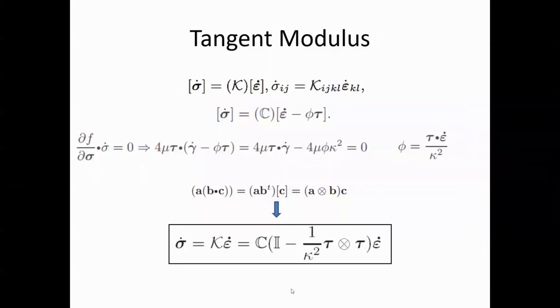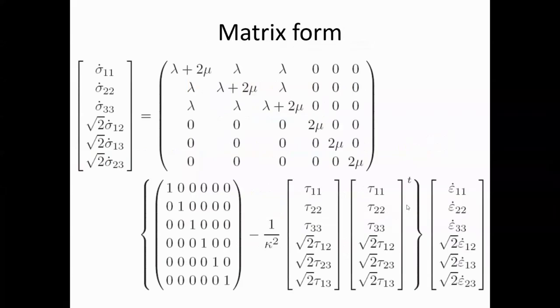Yeah, you can call it instantaneous increment in stress to instantaneous increment in strain. The relationship between these two is called the tangent modulus. If I had taken sigma and epsilon over here, I would have gotten secant modulus. Got it? Yes, sir. Let me proceed.